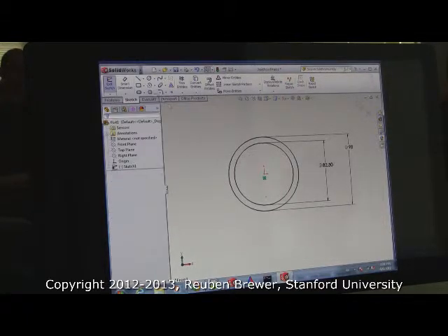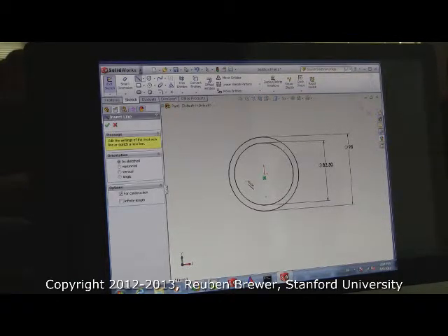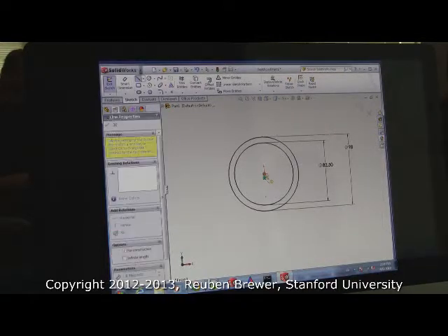So I want you to take, you see here on this line button, there's a little arrow. That little arrow lets us access all of the types of lines. So go ahead and take a dashed line and put one end in the center and click, and don't click again. Let's play with this line for a sec. See how I can drag this around? SolidWorks is going to do a couple things.